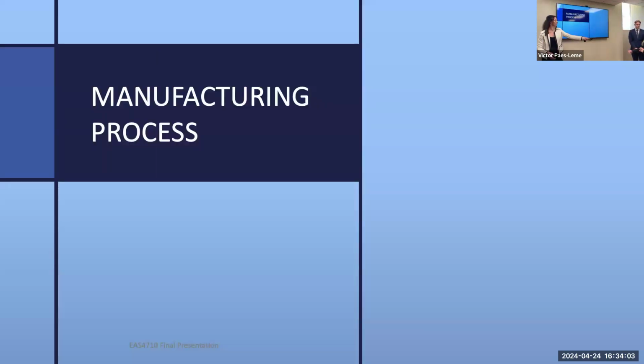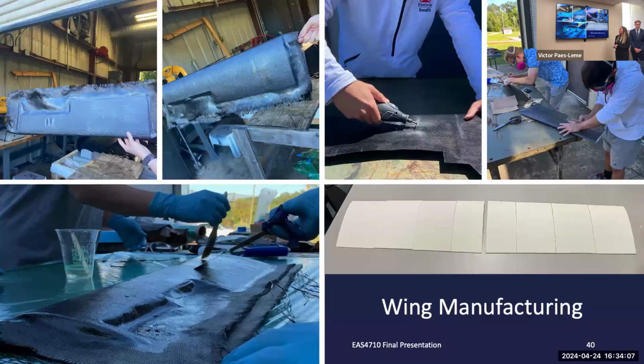And now to talk about our manufacturing process, just breaking that down. For starting off the wing, we 3D printed the wing with lightweight PLA, as the people that are here can see on the table. And here is another visual though. And with these sections, we glued them after post-processing them and sanding them down. We glued them together to make it one complete piece.